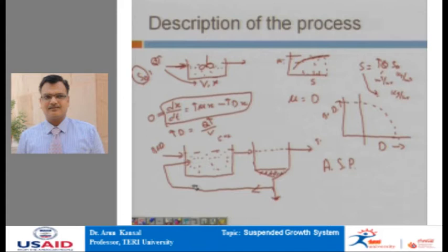So, question comes, how is this bacterial concentration getting increased? Let us take an example. Suppose the yield factor of this, now remember the yield coefficient. Yield coefficient is the amount of biomass produced per unit amount of BOD consumed. So, suppose for a given yield coefficient we get say 0.5 kg of biomass per day, which means that for a given level of BOD and supply, this system is able to produce 0.5 kg of the biomass.